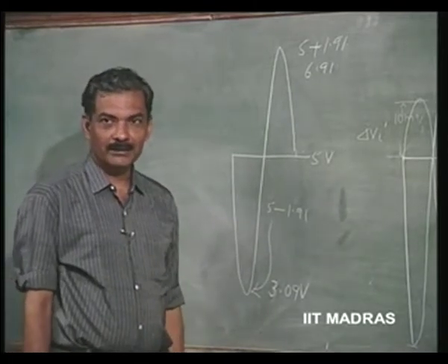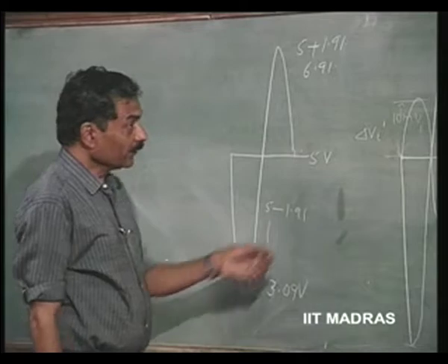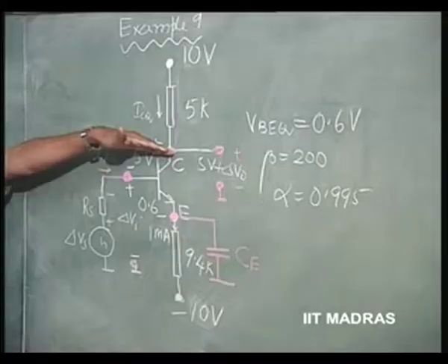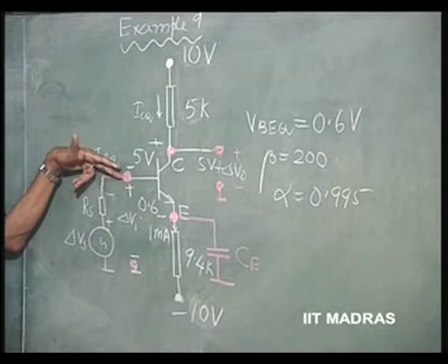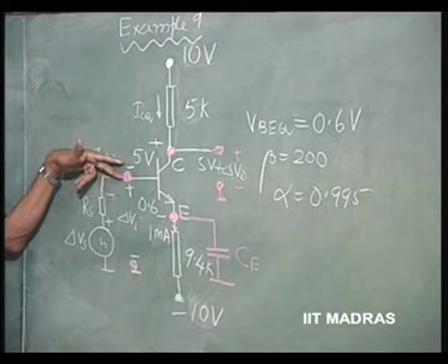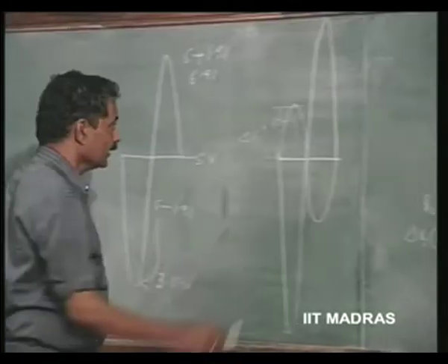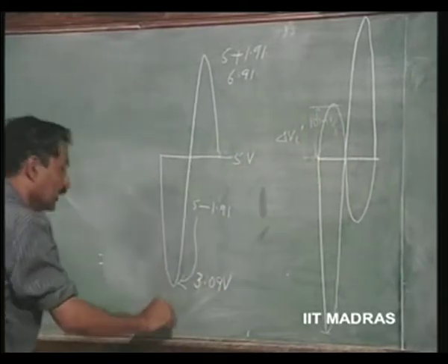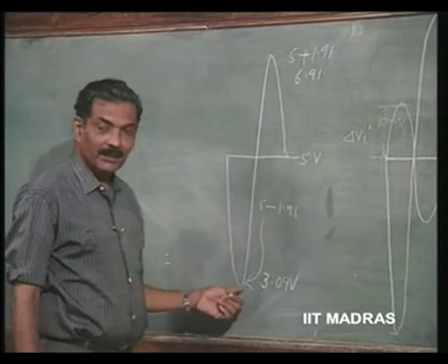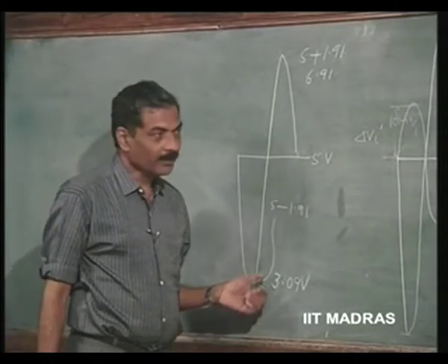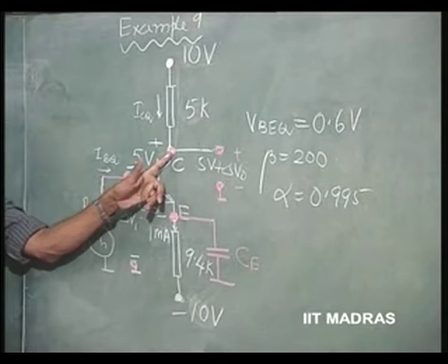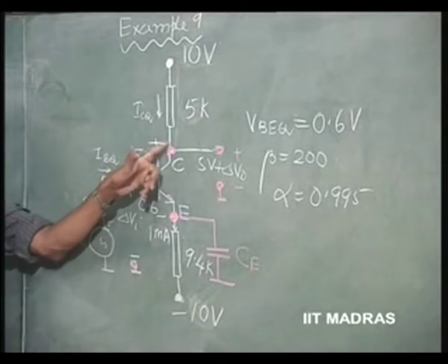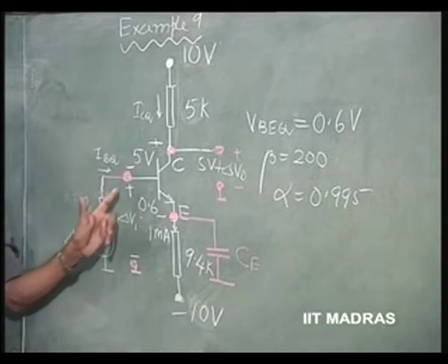When this is happening, this voltage here is going to decrease. Up to what value can it go on? It can go on until this voltage becomes equal to 0. This I have told you. VCB equal to 0, it is entering the saturation. That means if you keep on increasing this signal, this point will be coming towards a point where this voltage is nearing 0. This is already close to 0. Then VCB is going to be 0. Then the transistor enters saturation.